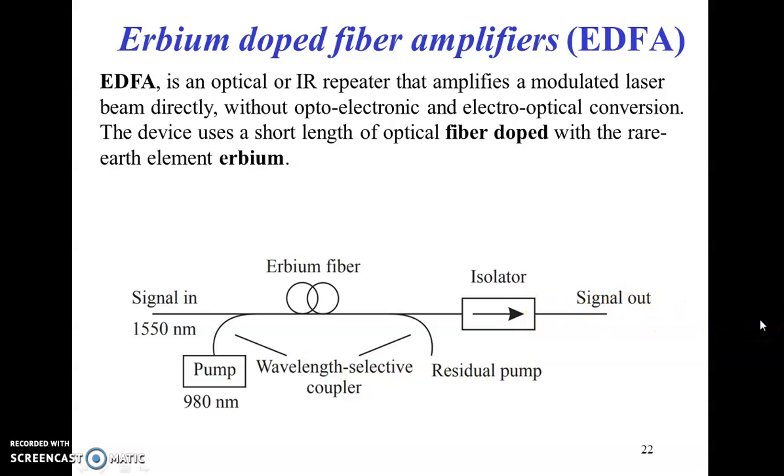Several factors have made EDFA the amplifier of choice in today's communication systems, because of the availability of compact and reliable high power semiconductor pumps, and the fact that it is an all fiber device, making it polarization independent and easy to couple light in and out of it. So it is very easy to get light in and out of this fiber.